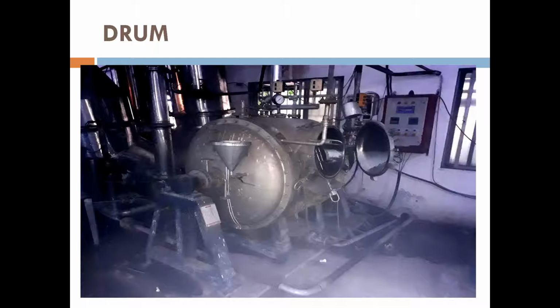It is just like a high pressure horizontal drum, and it has a perforated basket in which fabric is loaded, and water is filled in the machine. The lid is closed, and then the temperature is raised to say 130. It is only plain water, and under the heat and pressure, the yarn of the fabric shrinks, and the fabric is shrunk.